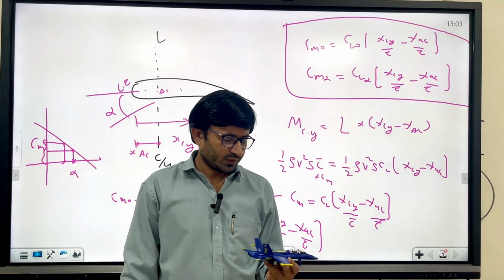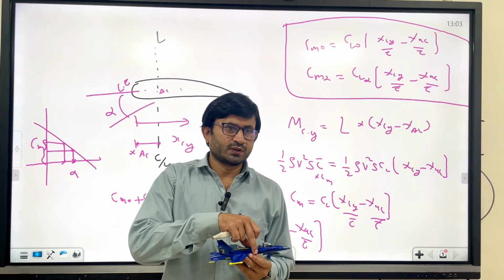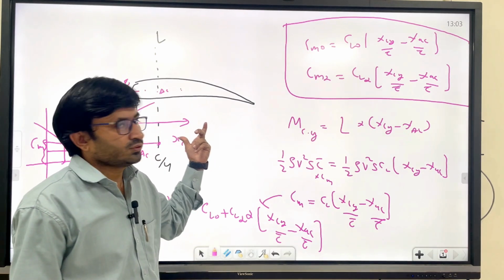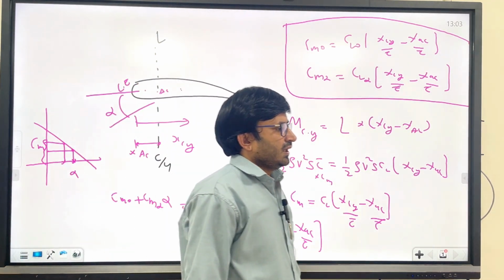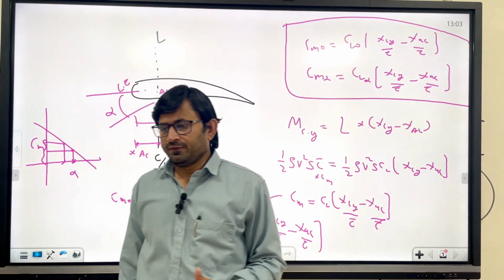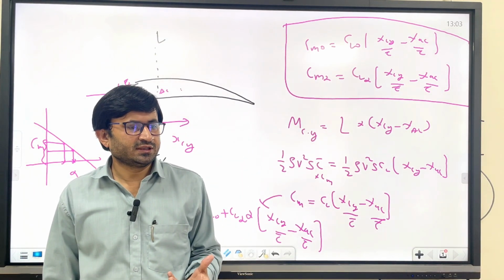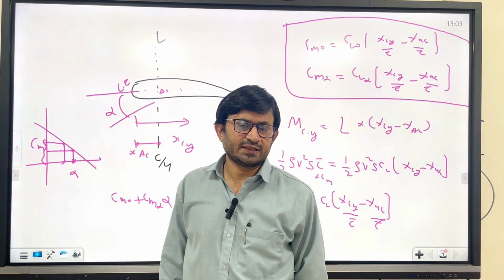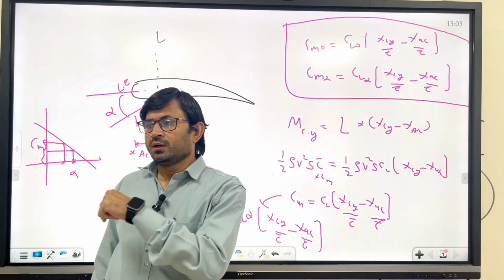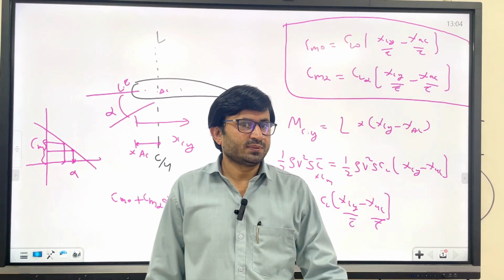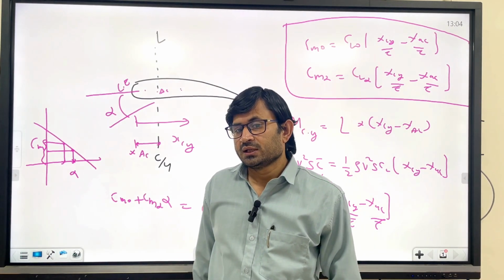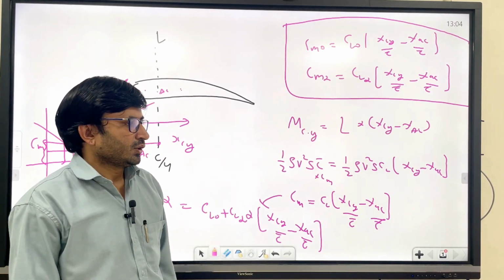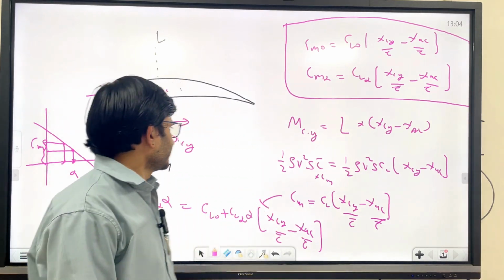Whether you place a high wing, low wing, or mid wing configuration, this criterion should be met. So I mean to say that wing position generally does not affect static longitudinal stability much. However, when I teach you aircraft lateral and directional stability, you will see the low wing and high wing configurations play a major role in roll stability and directional stability as well.